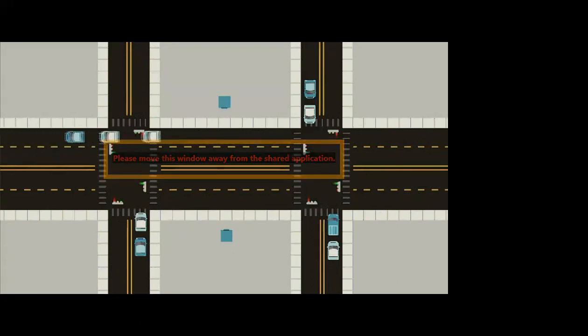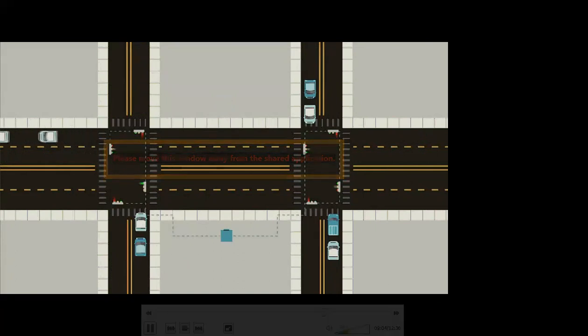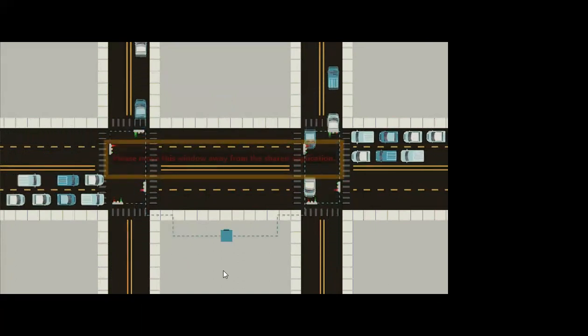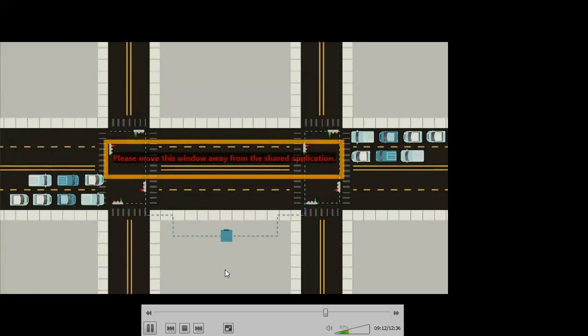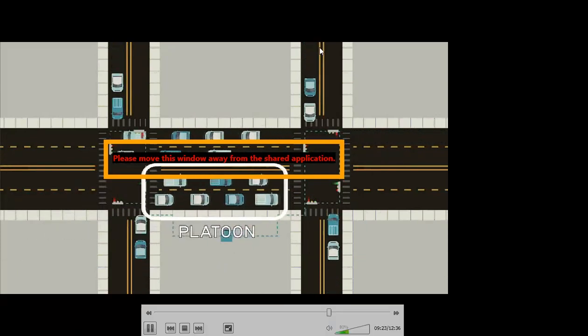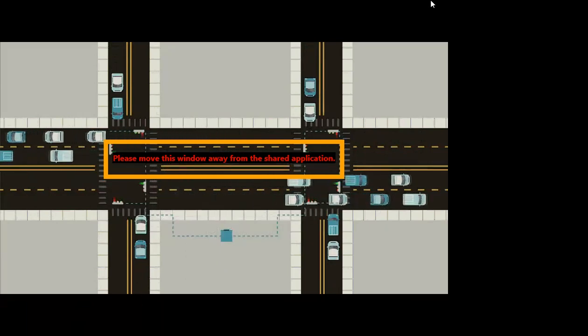One solution to this problem is signal coordination, where lights can not only consider the traffic waiting at their intersection, but also the status of nearby signals. This is a very common configuration on long corridors with relatively minor but frequent cross streets. The signals on the major road are timed so that a large group of vehicles, called a platoon by traffic engineers, can make it all the way through the corridor without interruption.